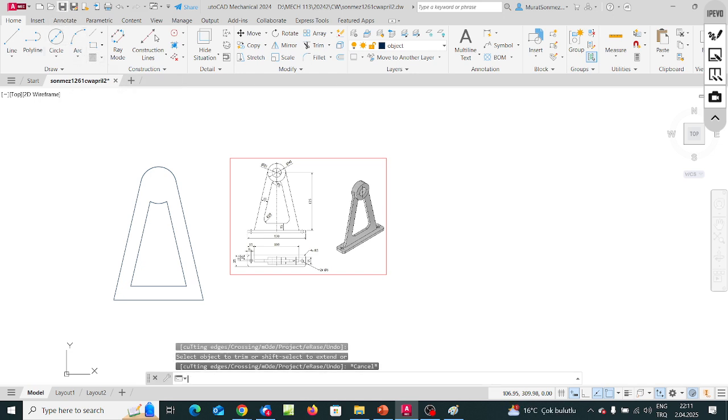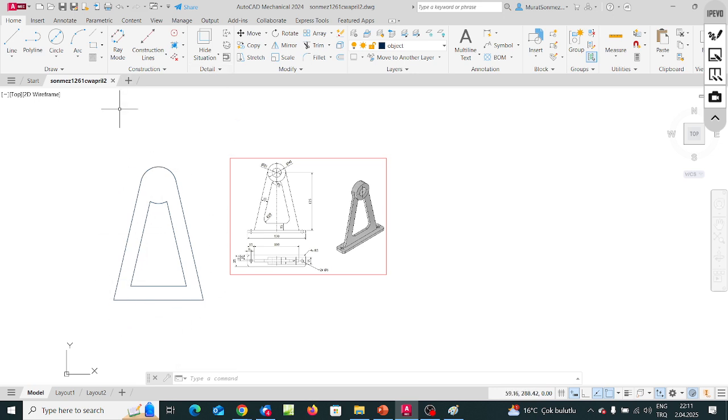Okay then, save the file one more time, and then convert this figure to a region. Since I created the segments using single line and circle creation tools, although it's a closed boundary, the lines are not in continuation, the terminal points of the lines are not coinciding with each other, so it is necessary to convert the figure to a region.